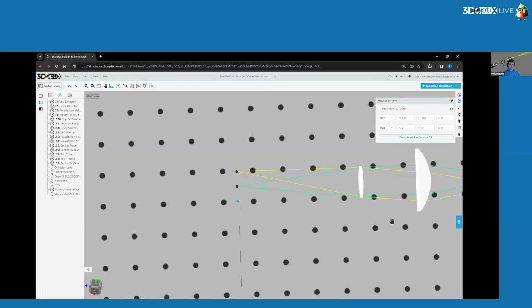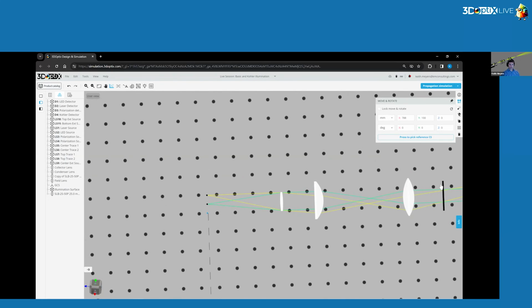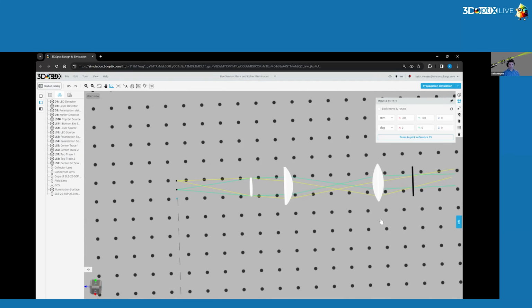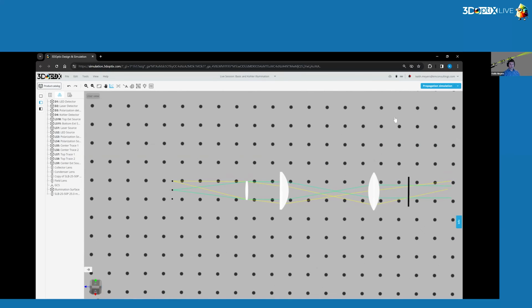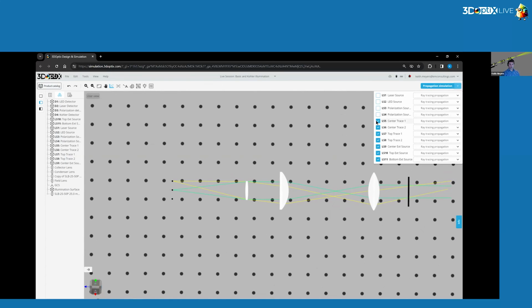We want to see how this propagates through and what the illumination is at that Kohler illumination point here, where they're all parallel and incident at the same place, crossing. Okay, let's go ahead. We will turn off our trace rays, and we're just going to use the 3 extended source points here.